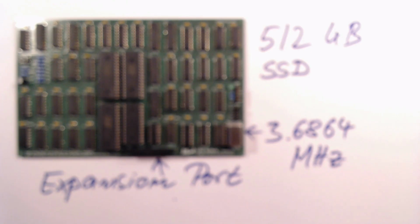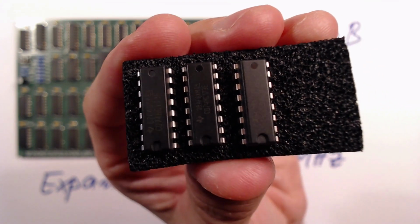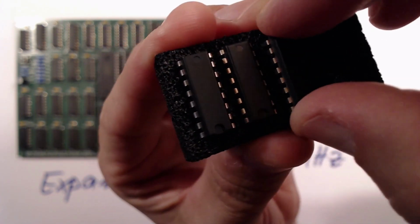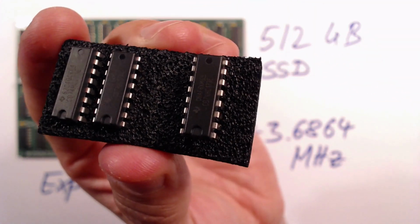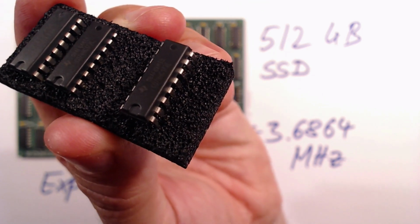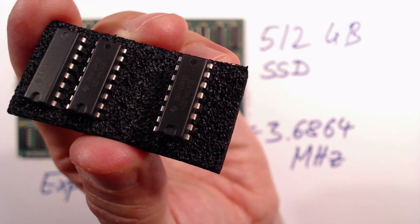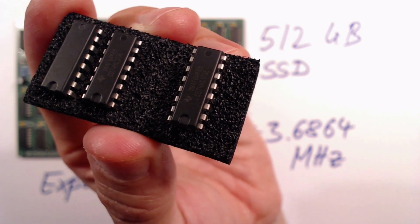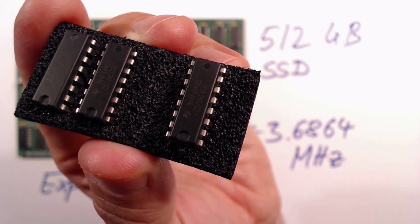What if we control the upper address lines with this 4-bit 74HC173 latch or register instead? We only need to come up with a way for our CPU to control this. There are basically two approaches. We could memory map a specific RAM address to this register. We would need to build a circuit that detects whenever our CPU writes to that address and then copy the bus value over to the bank register.